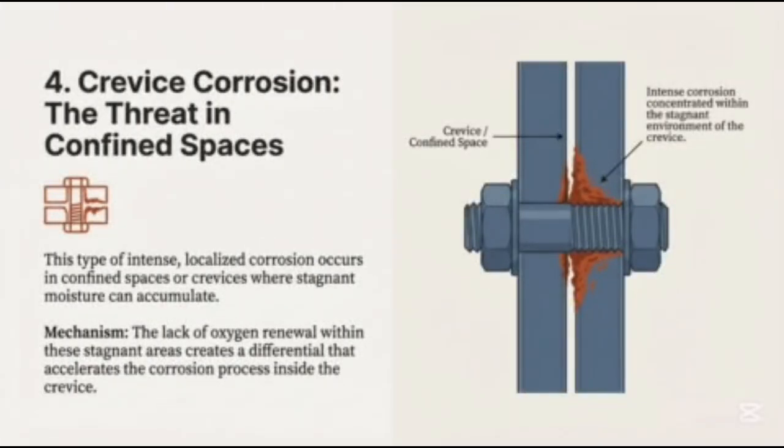The fourth type of corrosion is crevice corrosion. This type of corrosion occurs between closed surfaces or in narrow spaces. It's caused by the difference in the percentage of oxygen between open air and narrow spaces. It affects the joints of the surface, which makes them weak and reduces their durability.